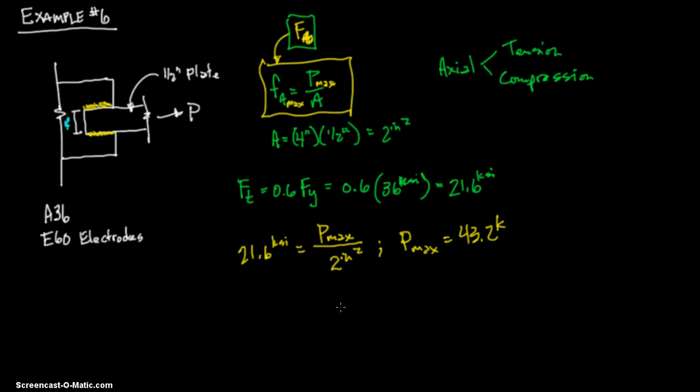It says not greater than the thickness of the material minus 1/16 inch. Okay, so we have 8/16, so that'd be 7/16. Max is 7/16 inch. I hope that makes sense, because we're doing the thickness of the material minus the 16th inch. It says unless the weld is especially designed on the drawing to be built out to obtain full throat thickness. And we don't have that circumstance, I'm assuming. So let's max out the weld.